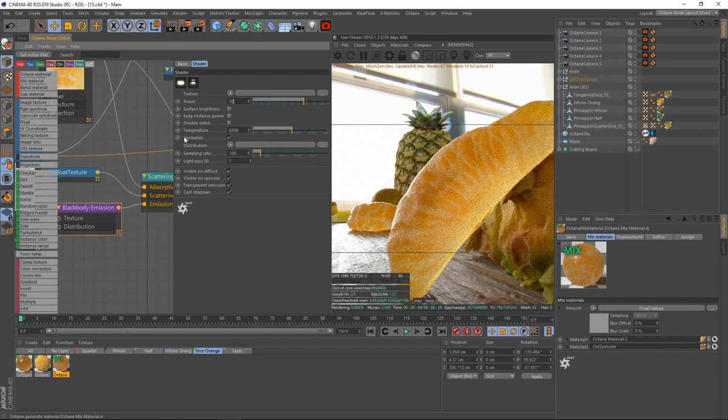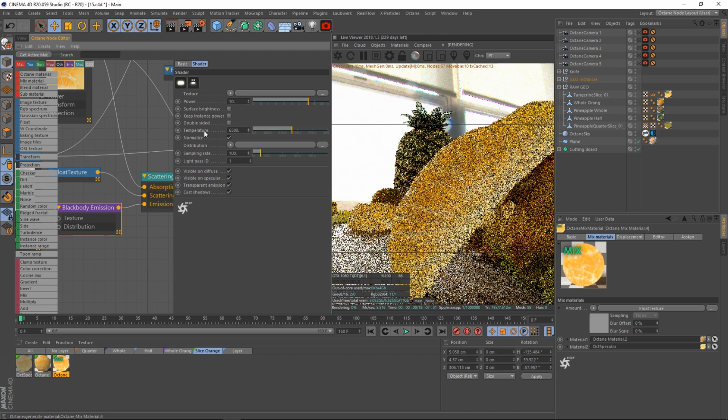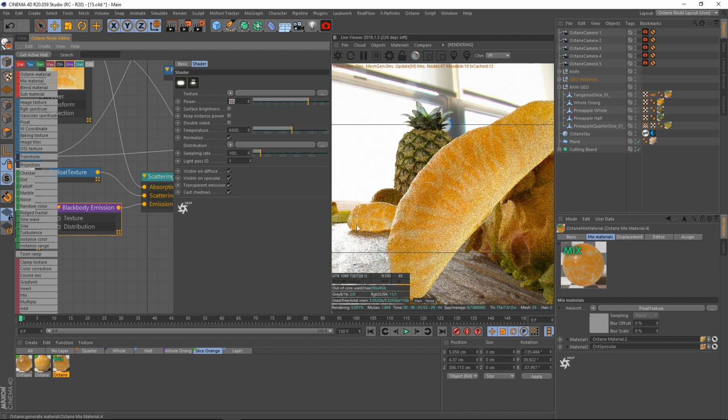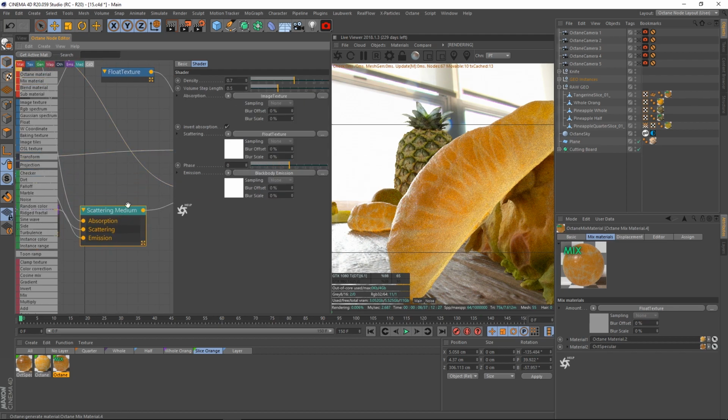Now, you don't want to go too high. Again, if I set this to like 50, then it becomes a flashlight. Not what we want, right? So we can drop this to 10. Still too bright. Look at this background one here. Very fake looking. Drop it down to 4. There we go. Nice and beautiful. Looks very tasty and inviting, like something you'd want to eat. Definitely looks alive and healthy.